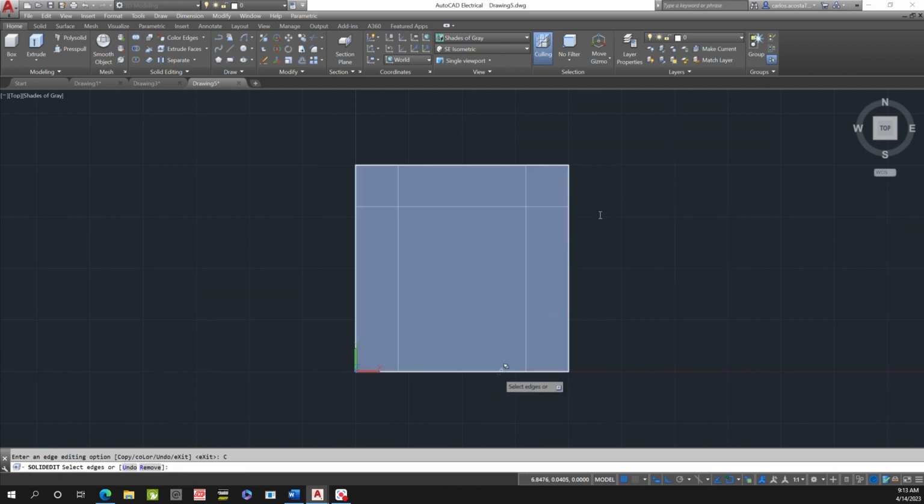And we're going to do it again. So like this edge right here and the 3D solid. And if you wanted to create more copies, you could, but at this point I only need that one, so I press enter. And then I select the point, and I go inwards for 2 inches. Alright, now we have these references where we can draw the circles.